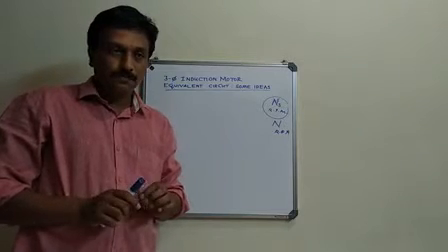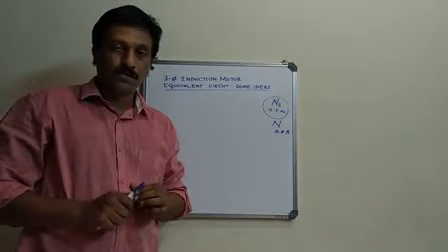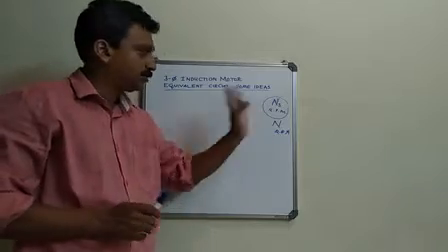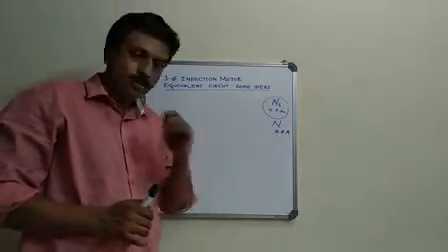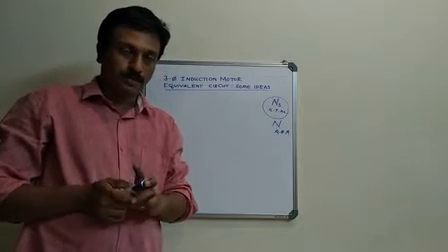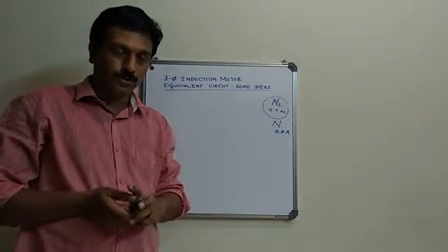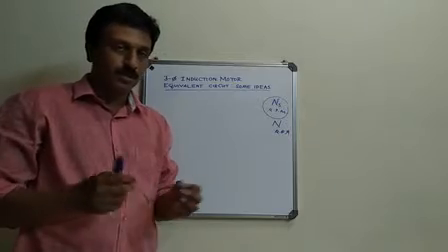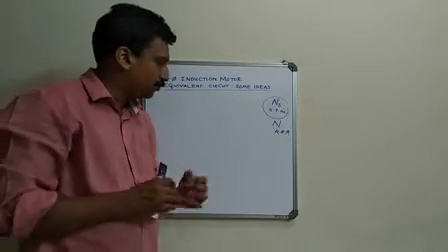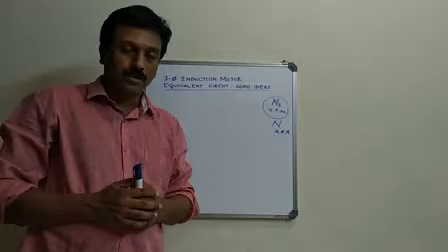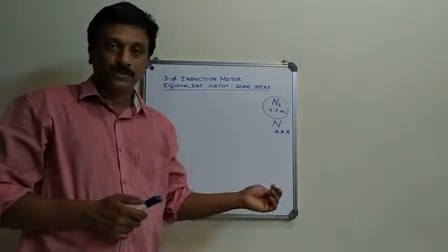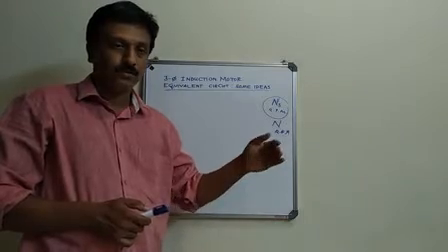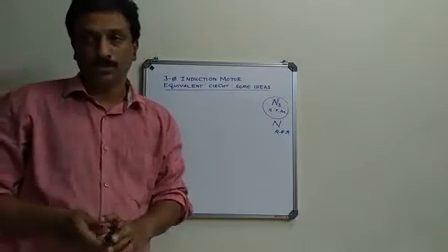In the ideal case, if there are no losses, it will run at the synchronous speed. In the practical case, there are mechanical losses, viscous friction and bearing friction, all of which retard the speed, so it runs subsynchronous, closer to the synchronous speed.